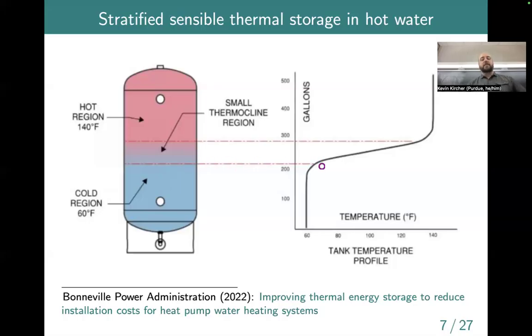Well, okay, so I'm not sure about the steepness of the thermocline. I guess the point I was trying to make was if you had a really conductive fluid, I'm actually not sure of an example, but maybe a liquid metal like mercury is really conductive. Then you would have faster heat transfer between the hot layer and the cold layer via conduction. So I think over time you would tend to degrade the stratification here. I actually don't know if that would translate to a steeper thermocline or not. Anybody want to hazard a guess?